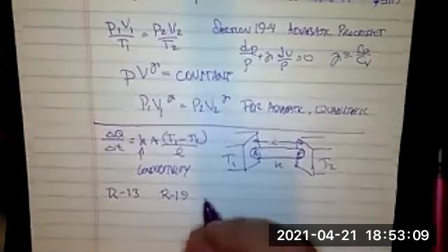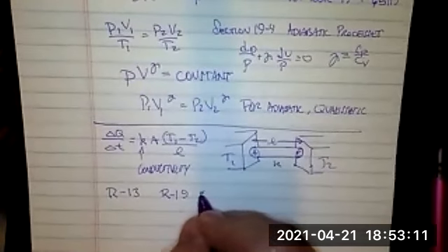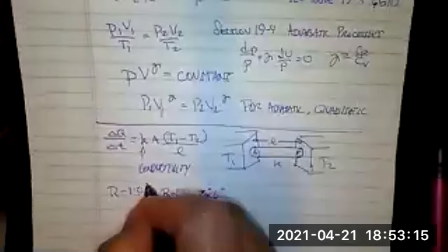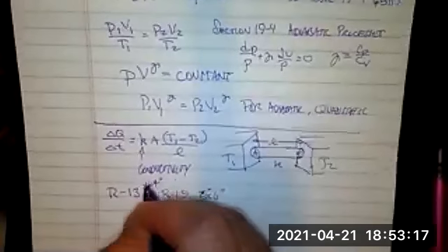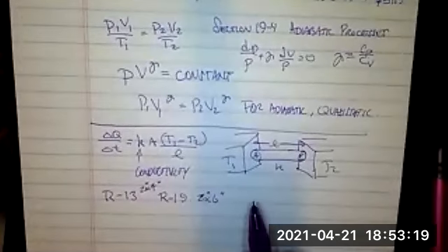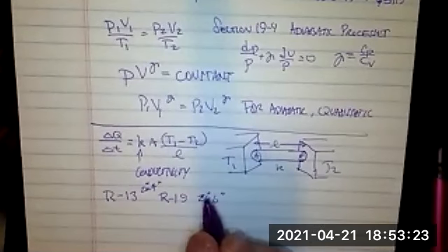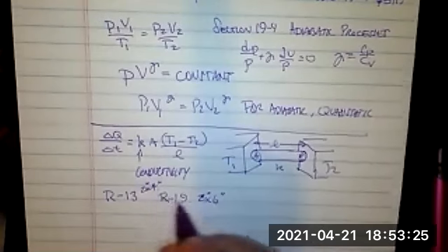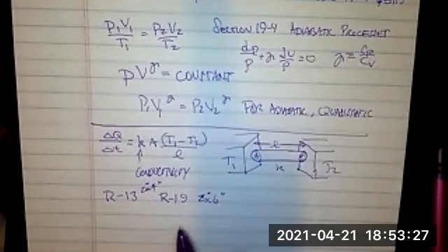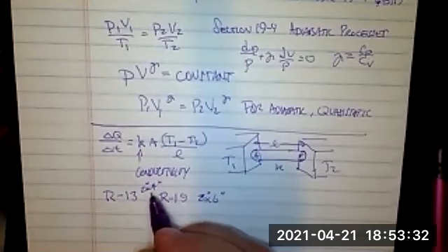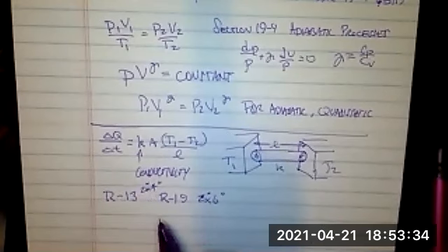R19 is really supposed to be for 2x6 walls, and R13 is supposed to be for 2x4 walls. Often people will say, if this is R19, I will really save a lot of money by stuffing it in my 2x4 wall. And they'll actually just be wasting a ton of money, and in fact get worse results than if they used R13.